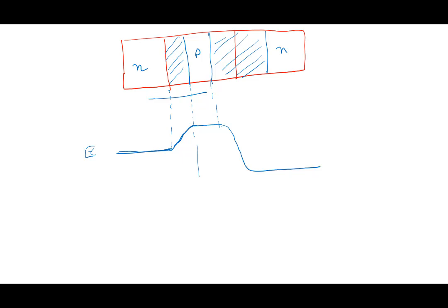All of you might have seen diagrams like this. If I've applied a reverse bias on the collector depletion region, a voltage equal to, say, 2 volt, let's say this is 2 volt. The base-emitter junction is this thing here. Now the issue is, why does the current not flow? Because there is a big barrier here, the built-in voltage. This built-in voltage is of the order of, we'll show you some calculation, maybe 0.9 volt. So an electron cannot cross this particular barrier. It cannot happen. So no current flows in this case.